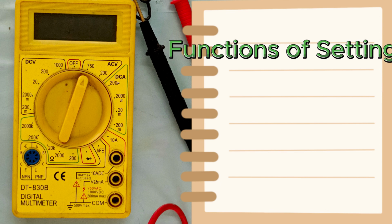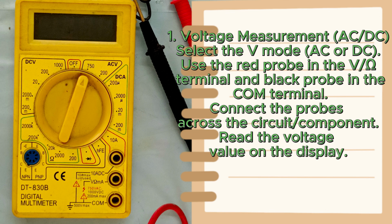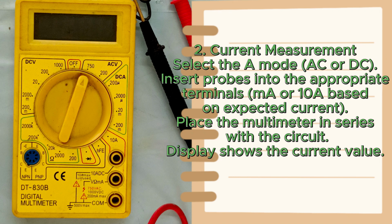Functions of settings. 1. Voltage measurement, AC/DC. Select the V mode, AC or DC. Use the red probe in the VΩ terminal and black probe in the COM terminal. Connect the probes across the circuit component. Read the voltage value on the display.